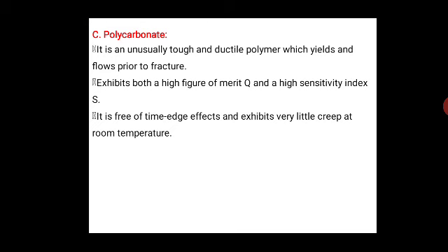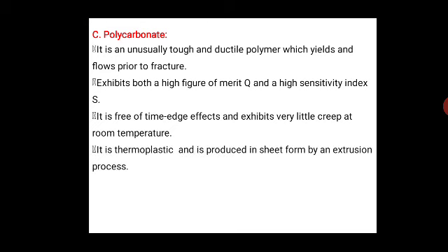The birefringence introduced in the plastic state is permanent and is locked into the material on a molecular scale. Therefore, this behavior makes the material suitable for many three-dimensional photoelasticity studies.